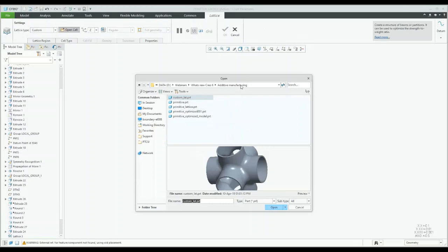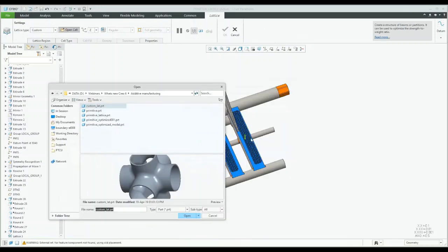This specific one is not going to work in this scenario, but it's just a normal part that you draw up and use within your lattice tool. Just a few things to remember when you do that: try to use your default accuracy settings, just to make it a little bit quicker so you don't spend too much time on regenerating things like that. Just keep that in mind.